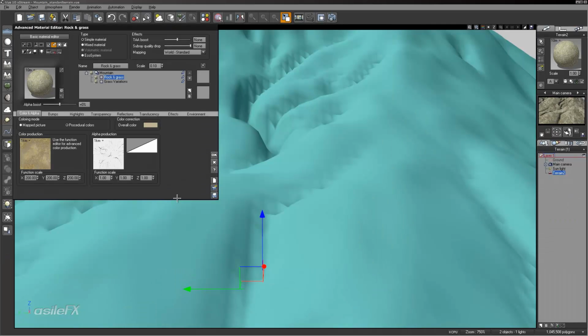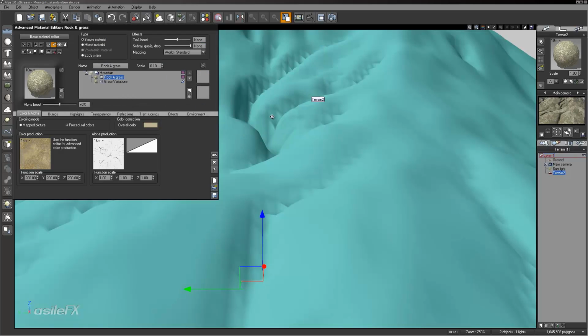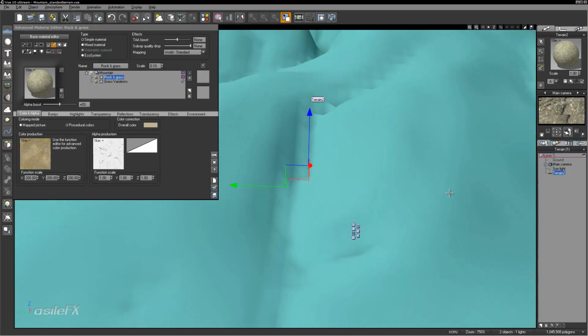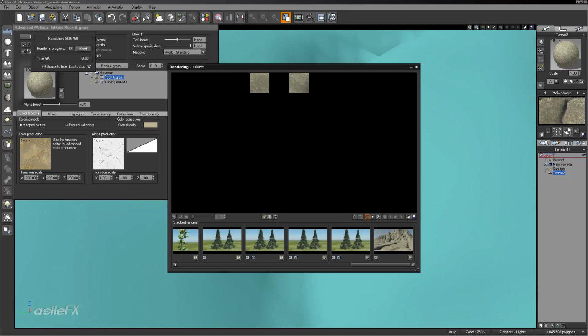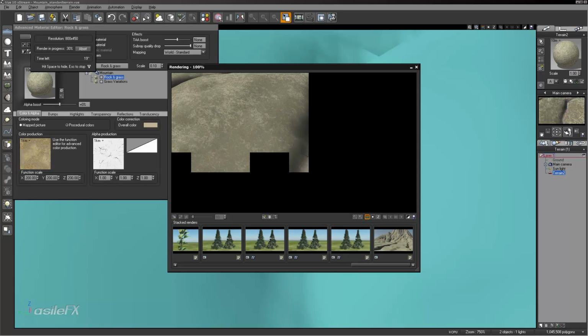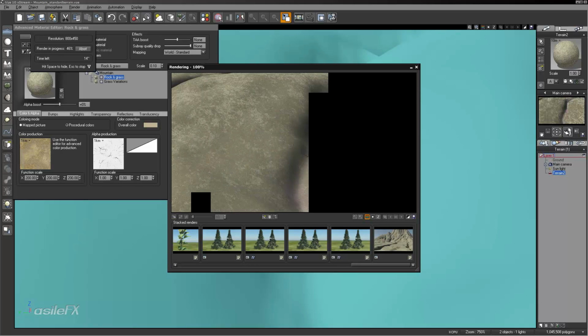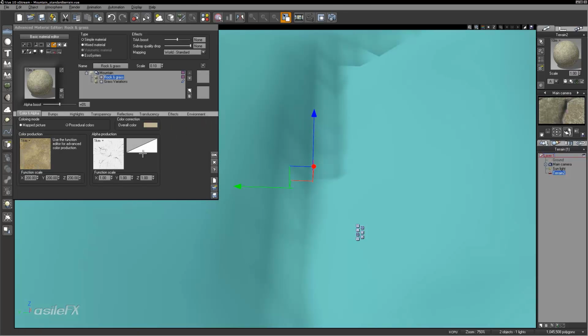Now an easy way to tell where a surface is by using the material layer highlighter. Every layer has a highlighter, and what you can do is just go ahead and click on the little highlighter icon, and then we could right click and select a color that will show up, something a little more violet in this case. You can see that starting to show. And the main problem, I think, with this terrain is just that the resolution is probably too low, which is why those small little cracks aren't really filling in with too much of the material. But you can start to see where that material is showing up. It's definitely the scale of the texture.